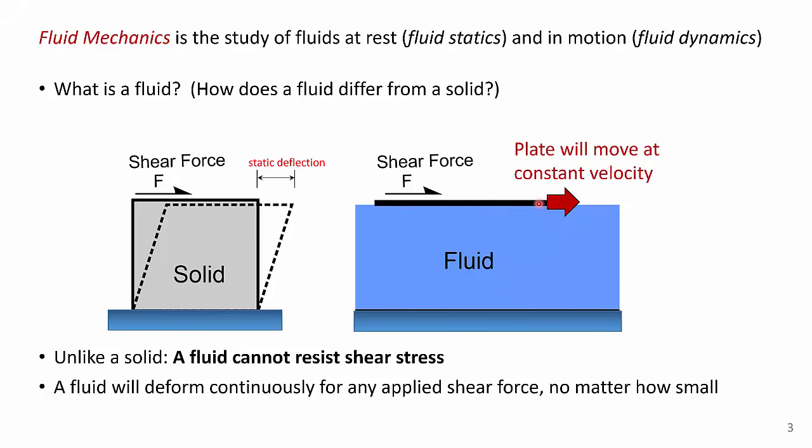And the interesting thing about a fluid is the plate will have a constant velocity. Of course, it'll accelerate at first, but then it'll reach a constant velocity, and it'll have a velocity no matter how small the shear force is. So unlike a solid, a fluid cannot resist shear stress without continuous deformation. A fluid will deform continuously for any applied shear force, no matter how small. So that's the technical definition of a fluid.